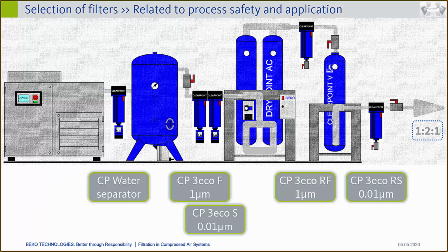Remember, we talk about process safety, which is the priority here. Any abrasion inside the desiccant beads will create dust, and if there's no dust filter in between, all the dust will be collected on your activated carbon. This gives two results: it reduces the active surface of the activated carbon, and it increases the pressure drop for the air passing through that tower.